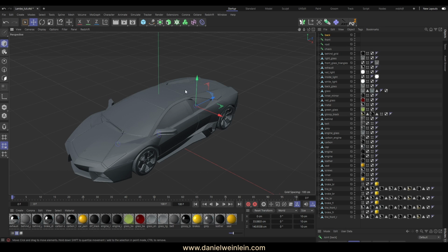And I need these two joints for creating the drift behavior inside Unreal Engine, because later I want to create an IK for them. So we put the back joint underneath the front joint, put the front joint underneath the root joint, and then we put the chassis joint underneath our front joint. So everything gets related to the chassis.